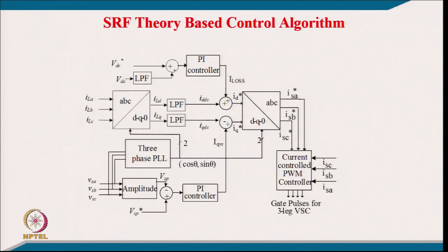Well, we have another control algorithm which is a very famous algorithm, the synchronous reference frame theory based control algorithm. This is DQ theory, which is used in electrical machine analysis as well as in vector control of the motor drive, the AC motor drive. This is the same algorithm which was used for the first time by the Wisconsin group, and it is reported widely and used for a lot of systems, including not only D-STATCOM but also active filters as well as solar inverters. So, plenty of places use these.